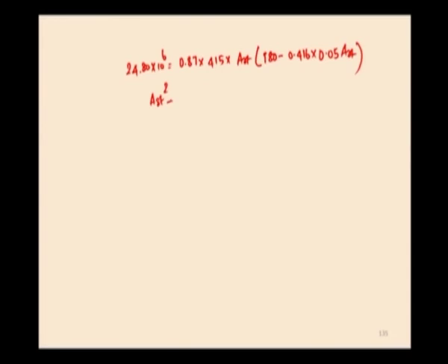minus 8653.64 AST plus 3.30 into 10 to the power 6 equal to 0. This is the one. So, here the AST we have found by solving this quadratic equation, we are going to get 2 roots. Since it is a singly reinforced section, we are going to select the minimum root, that is AST required here it is 400 millimeter square.